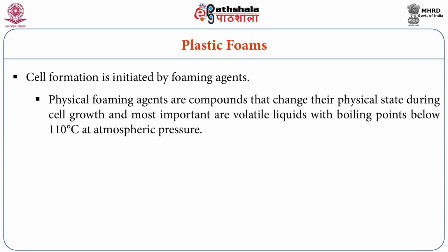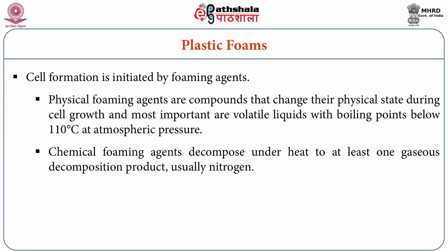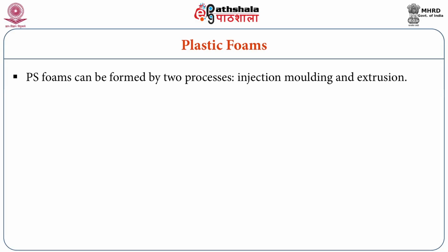Physical foaming agents are compounds that change their physical state during cell growth, and most important are volatile liquids with boiling points below 110 degrees centigrade at atmospheric pressure. Chemical foaming agents decompose under heat to give at least one gaseous decomposition product, usually nitrogen. PS foams can be formed by two processes, injection molding and extrusion.